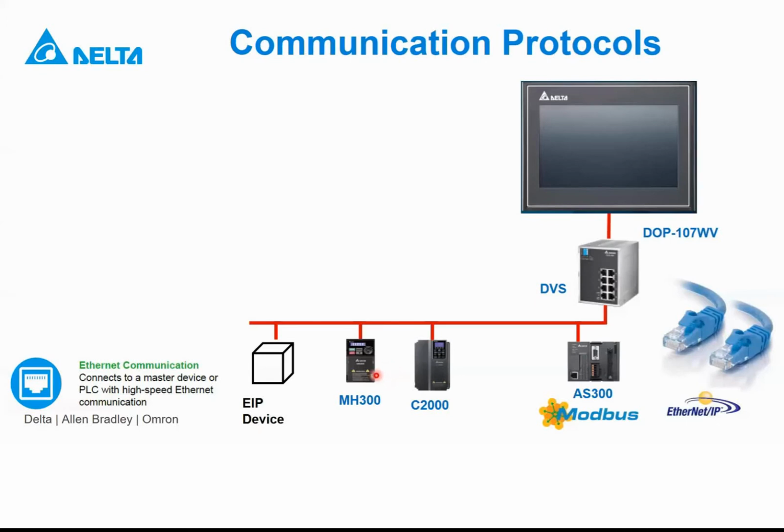So, talking about communication protocols. What are the communication protocols you can use to control your machine from our HMI? One of the communication protocols is Modbus TCP/IP. Modbus TCP/IP is an Ethernet-based protocol that is owned by Modbus. So I think virtually every controller on the market supports Modbus.